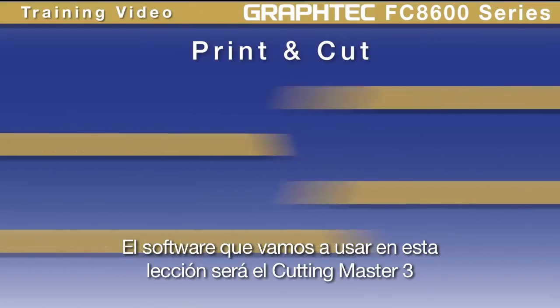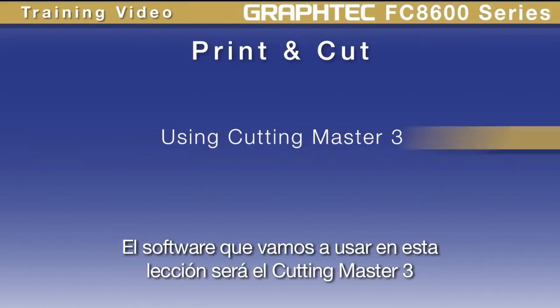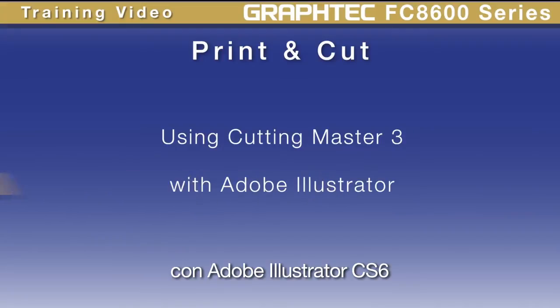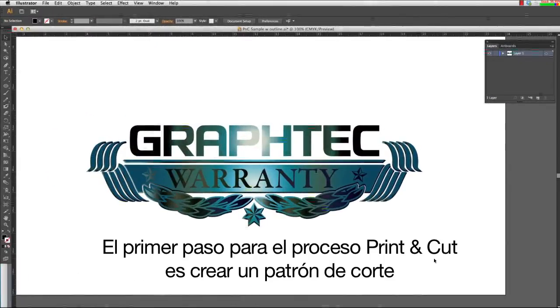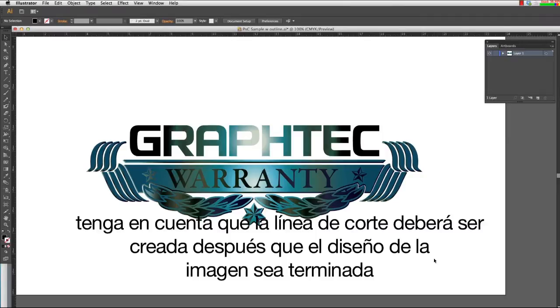The software that we're going to be using in this lesson is Cutting Master 3 with Adobe Illustrator CS6. While this may not be the software you're using, the process is similar. The first step to the print and cut process is to create the cut path. Keep in mind that the cut line should be created after the design of the image is complete.